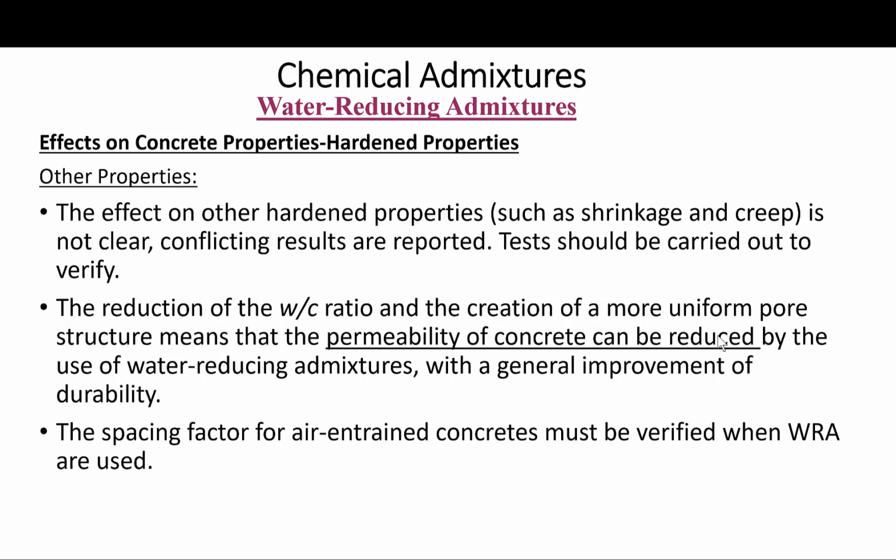But as we said, the reduction of the water cement ratio and the creation of a more uniform pore structure means that the permeability of the concrete can be reduced by the use of water reducing admixtures, with a general improvement in durability, just automatic.